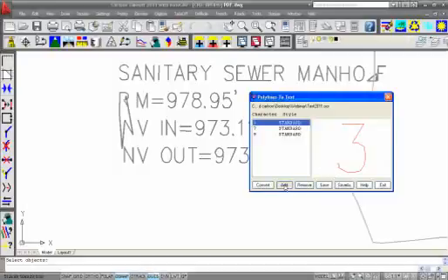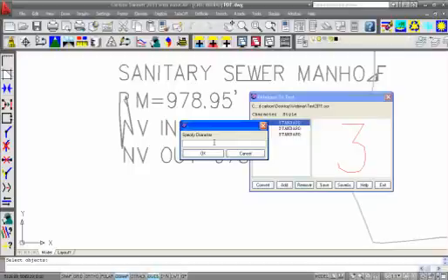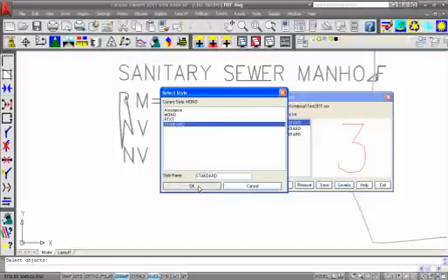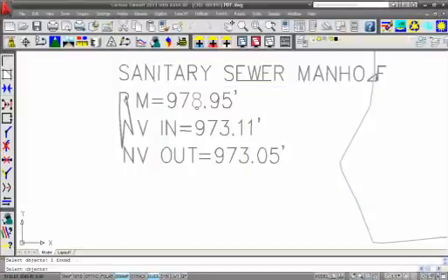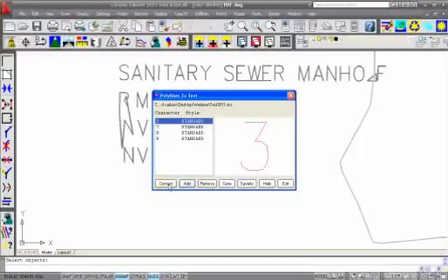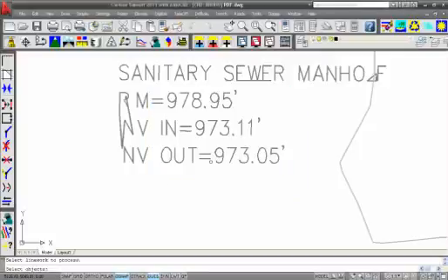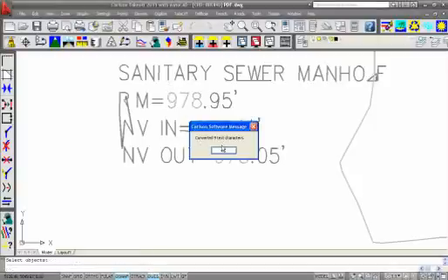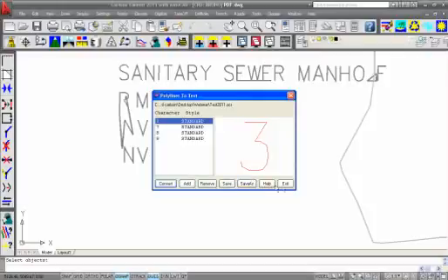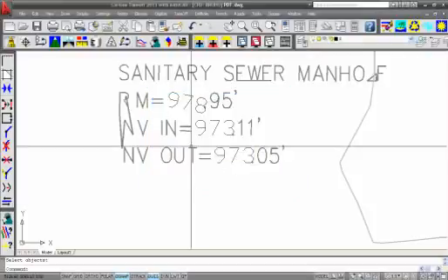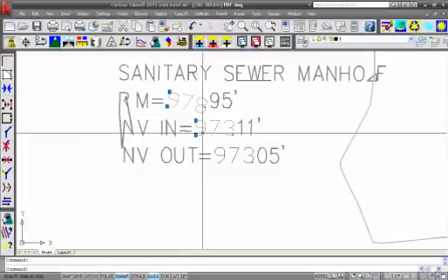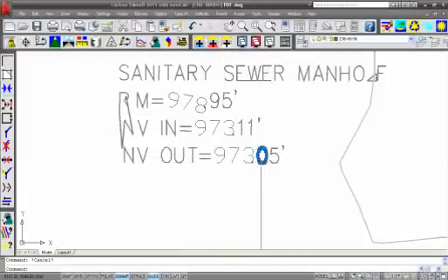Okay, and I'm going to add one more. Let's do 8. Standard, and I pick on that and enter. Okay, and once you build this library, I can say convert, and let's select this text here, enter. Okay, converted 9 text characters. Exit, save. Okay, and now I have text values for these instead of just lines.